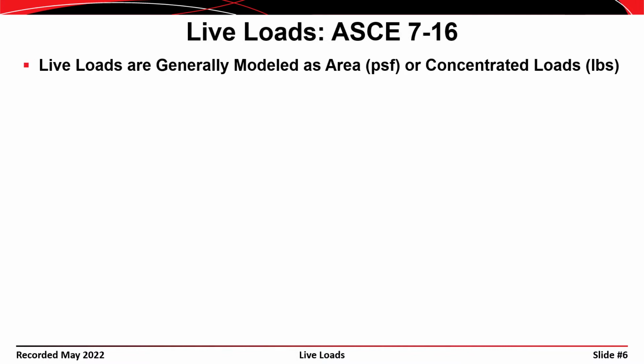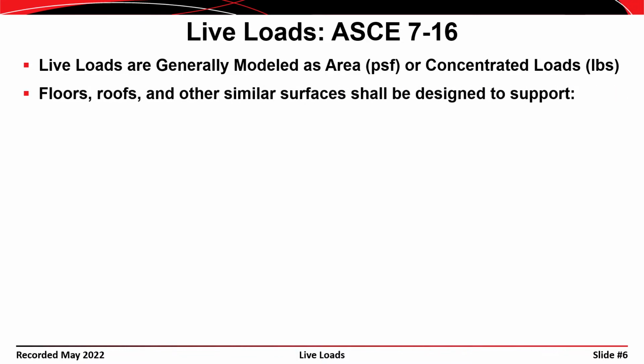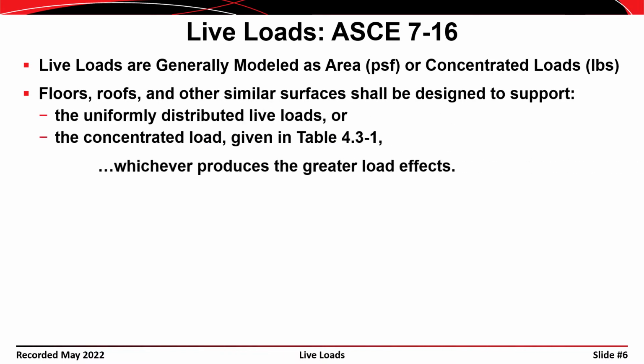Okay, live loads are generally modeled as an area load, pounds per square foot, but in a lot of cases we also consider concentrated loads as part of the live loading. Floors, roofs, and other similar surfaces shall be designed to support a uniformly distributed live load or a concentrated load that are provided in Table 4.3-1 of ASCE 7-16, and you take the results of whichever one produces the greater load effect.